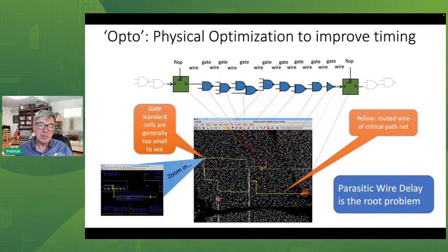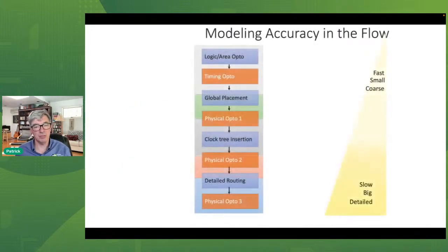So that's optimization. At that point, you can follow the exact path that the wire takes. Most of the delay that we have to fight is a result of the layer and the length of the wires. If we know that, we can massage the circuit a little bit to optimize the speed using several trickery that we have in the flow.